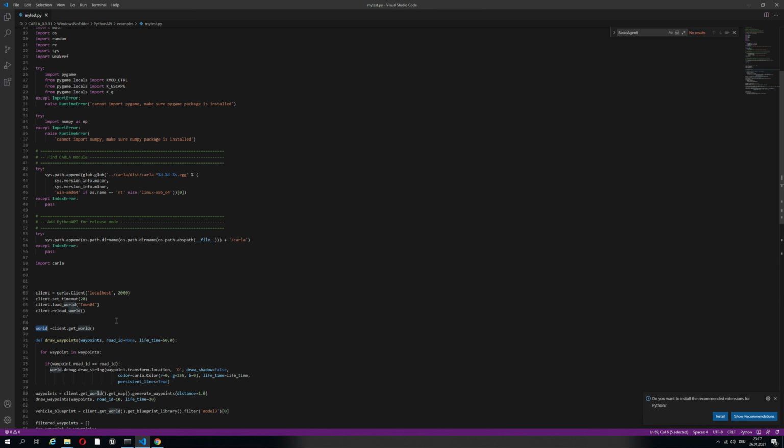First is using, for example, machine vision, which we'll see later. For example, you can use lane detection, where you detect the two lanes, and then with these two lanes you estimate the middle lane, which you can consider as the path.